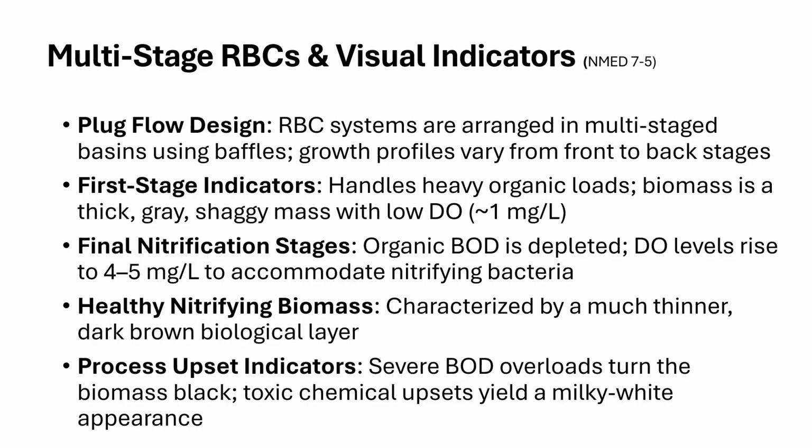The level 3 and 4 folks, you may see these, but likely you're going to see stuff like, what do you do in the event of a power failure? Well, you rotate the RBC 1/4 turn every 4 hours, but you can never tell.